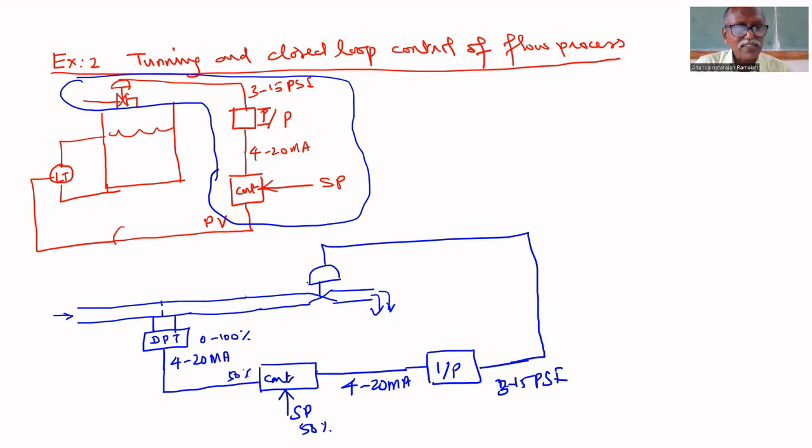The flow rate is adjusted by this valve opening. If you close the valve, it increases the resistance to flow rate. That's why flow rate decreases. But a pump here always pumps the same amount, but because of the resistance, flow rate decreases.